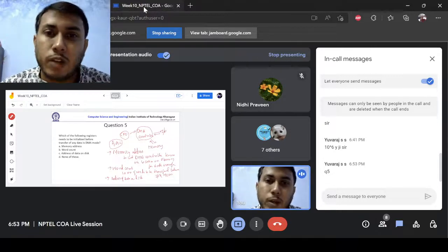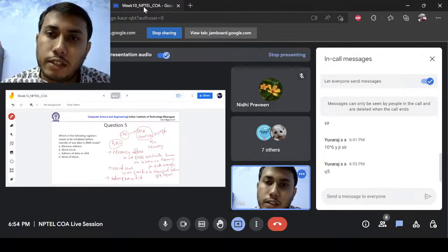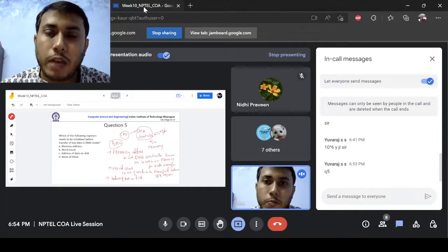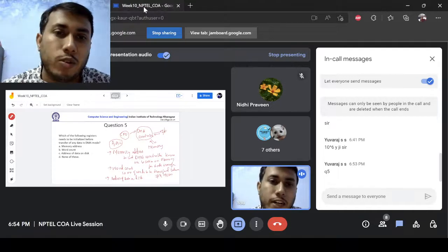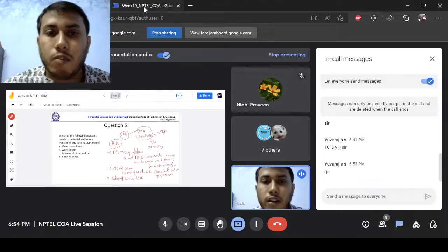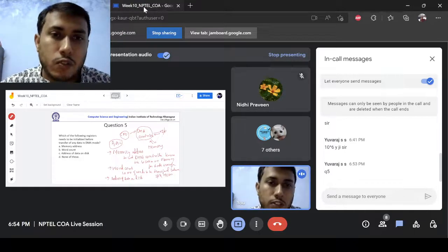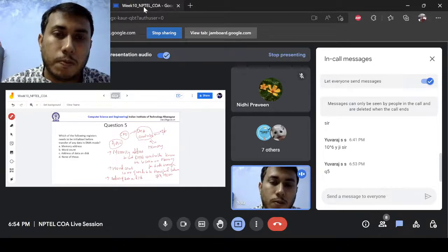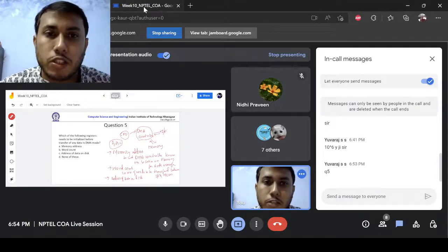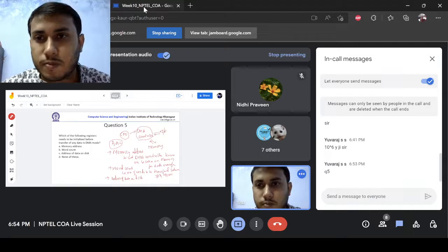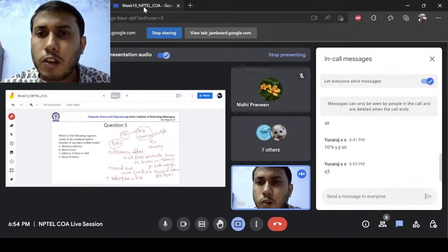So the DMA controller takes over all the functionality the CPU used to do for this transfer of data, and does the same job. In the meantime the CPU doesn't have to take care of this data and can do other work, because you know IO is one of the slowest procedures which the CPU executes. For this process, the CPU needs to tell it 3 things.